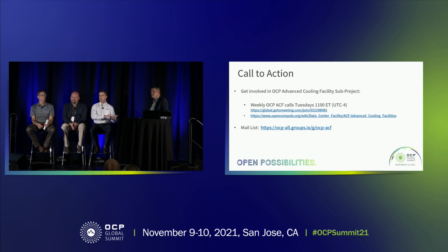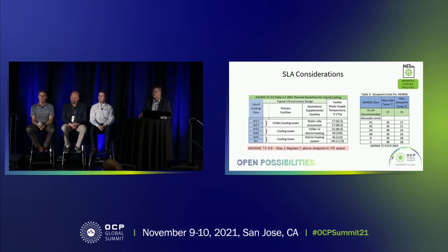But again, I go back to the statement that even if we're doing, say, a cooling tower only solution, and we're able to run off that cooling tower, let's call it 21 or 22 degrees C water, that we can send to the processors, you can still use something along the lines of desiccant dehumidification to drive your dew point down into the teens centigrade without using mechanical refrigeration, get rid of the insulation, get rid of the condensation risk. I think John's calling our time here.